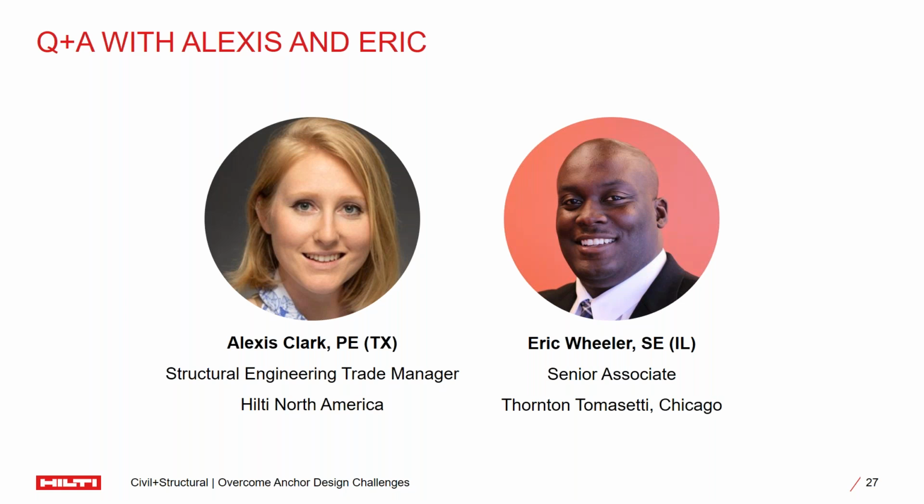So for each anchor that's in PROFIS Engineering, we have an ICC report that proves compliance with the building code. And those ICC reports are only valid for a certain window of time, typically 2 years for anchors, although they can also be updated for 1 year. With all of the testing that goes into publishing those values and updating those ICC ESRs every 1 or 2 years, we continuously have a specific ICC report for each anchor and each base material. So for HY200, we would have one for concrete, both cracked and uncracked, and masonry base materials.